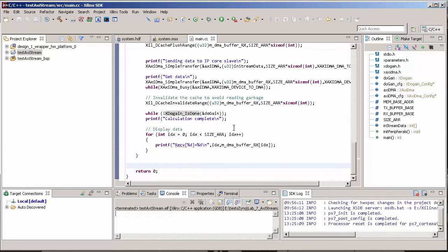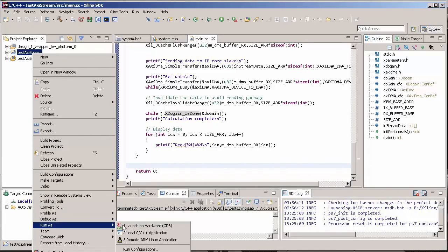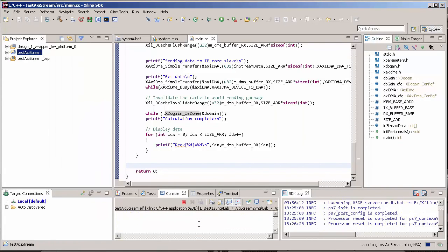Okay guys, now that we have our Zynq board, the ZedBoard, connected, we're going to run our software. You see it's quite simple. First thing, it's going to ask for a gain, for instance 5, to keep the same as what we did in Vivado HLS, and basically we got the same results. So let me just scroll up. Basically you're just multiplying everything by 5.